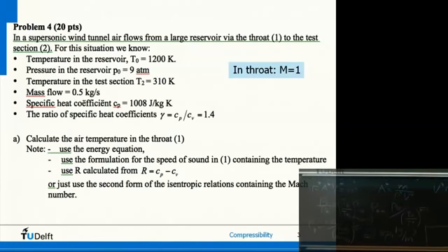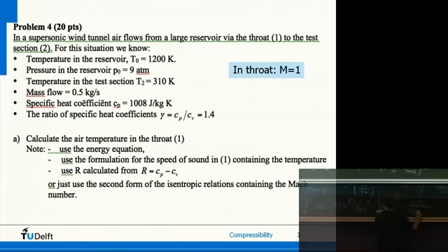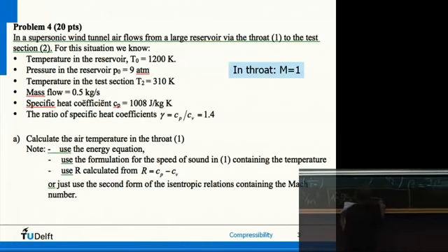Almost, because the question was the area in the throat. Mass flow we had, speed we had in the throat. Now we know the density in the throat, so now we can find the area through a very simple relation. A star is equal to m dot over rho star V star, so that was a half. Rho I just computed, 1.674. And V we had from earlier, 640. And then we find 4.67 times 10 to the minus 4 meters squared. So almost 5 times 10 to the minus 4 meters squared, or 4.67 centimeters squared.